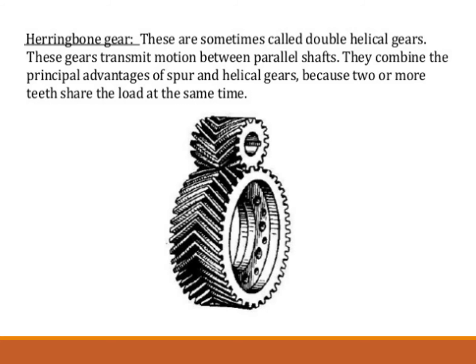Since such gears have a greater bearing surface, they possess exceptional tooth strength and heavy load carrying capacity. They stand up under continuous high speed operation better than other gears. Cutting herringbone gears is slower and more difficult, so they are most frequently used in larger sizes for heavy machinery. Herringbone gear is sometimes called a double helical gear.